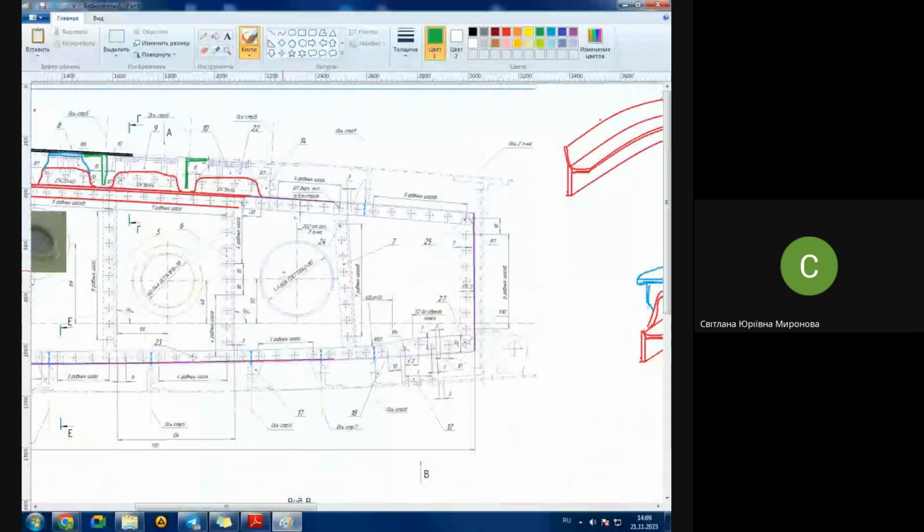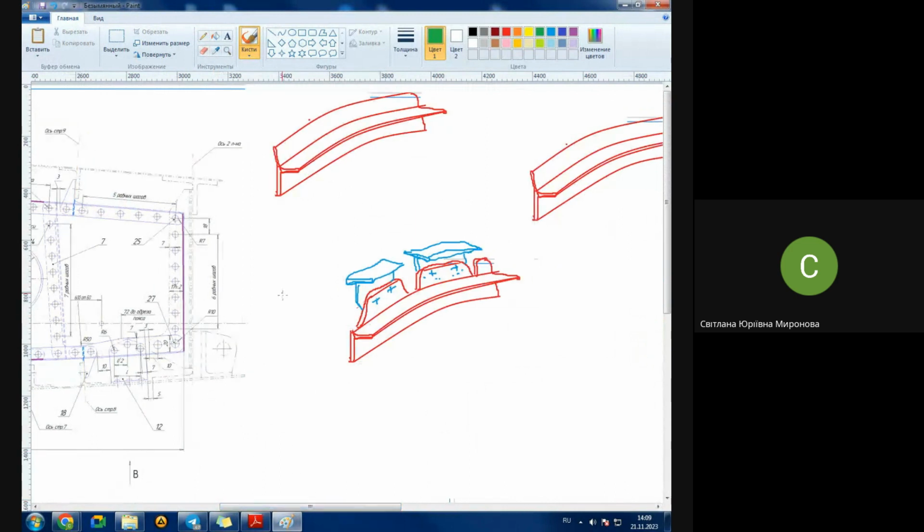And the longitudinal element of the rib itself, the cap, which also works with bending moment, but in another cross-section, in another direction, is also better not to cut. What we did with this trick, actually, this international trick. Look, which cross-section is working with bending moment in case of the rib? This one, the L shape. This L shape works with bending moment, and this L shape is not cut. What you are cutting is extra material at the top, and it's not really necessary.